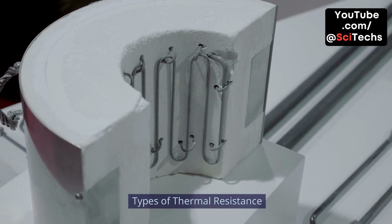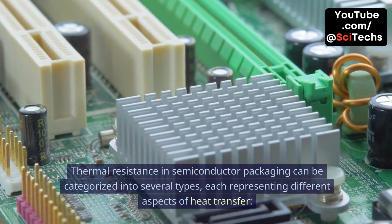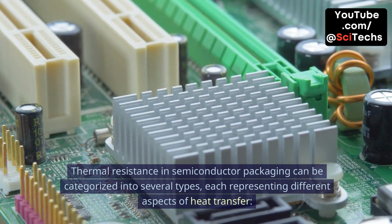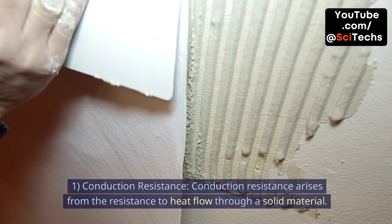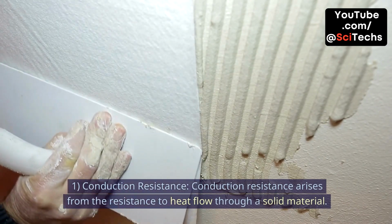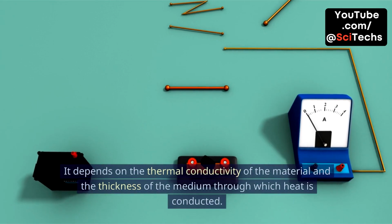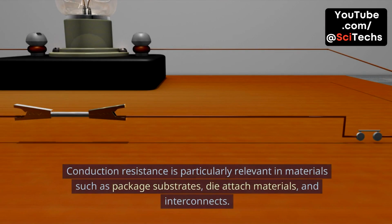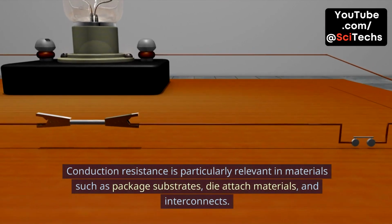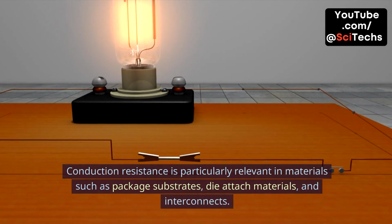Types of thermal resistance. Thermal resistance in semiconductor packaging can be categorized into several types, each representing different aspects of heat transfer. 1. Conduction resistance. Conduction resistance arises from the resistance to heat flow through a solid material. It depends on the thermal conductivity of the material and the thickness of the medium through which heat is conducted. Conduction resistance is particularly relevant in materials such as package substrates, die-attach materials, and interconnects.